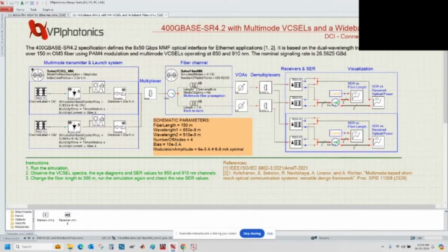Here we also have the multimode fiber, and we have a multimode coupler to just model the coupling between the VCSEL and the fiber. We're multiplexing the two channels here. We're doing transmission over two branches. One is 150 meters, and the other one is just 1 meter to represent the back-to-back case, but at the same time, keeping the effect of coupling with the coupler.